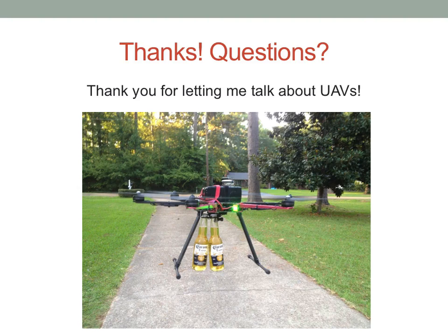However, to your next question, which software for the photogrammetric point cloud, Agisoft PhotoScan and Pix4D are the 2 software packages that I'm testing and working with. They both have their merits, as some do some things better, some do things worse. But I believe that Pix4D already has a built-in camera calibration model for a GoPro, so it takes care of that barrel effect for you, and you don't have to pre-process the images before you bring it into that software package.